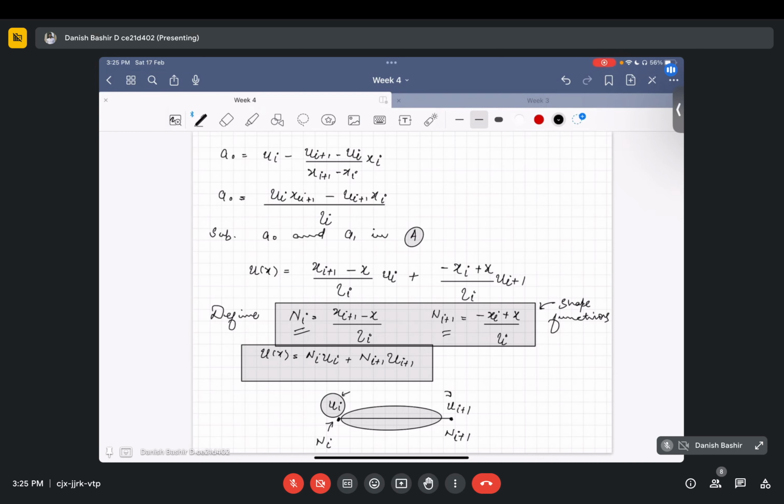We define Ni to be (xi plus 1 minus x) divided by li, and another for the other node. This Ni defines how the nodal parameter ui will have an influence on the rest of the solution, since we have to find the solution at other points within the element. It shows what the shape of the function will be if we plot it; that is decided by this shape function only. If I plot the graph of these shape functions, it shows the effect of the nodal parameter on the rest of the solution.